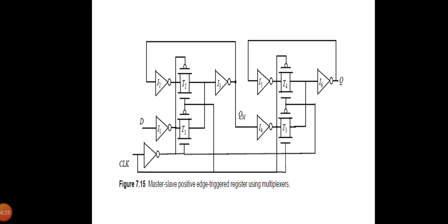plus TPD inverter. And the hold time represents the time that the input must be held stable after the rising edge of the clock, and in this case the transmission gate T1 turns off when the clock goes high. Since both D input and clock pass through the inverters before reaching T1, any changes in the input after the clock goes high do not affect the output. Therefore, the hold time is 0.